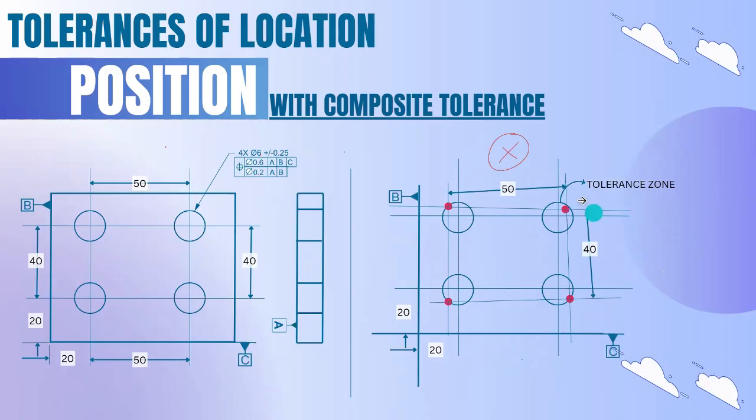But this is not allowable. Here this hole is located here, and this hole is located here, so it is breaking the pattern dimensions. So this is not allowed in this composite position.